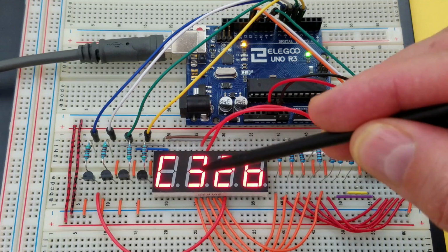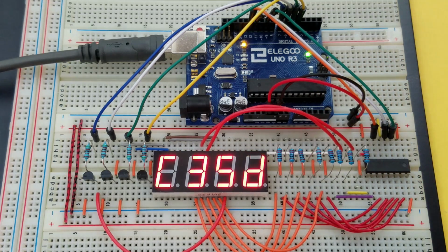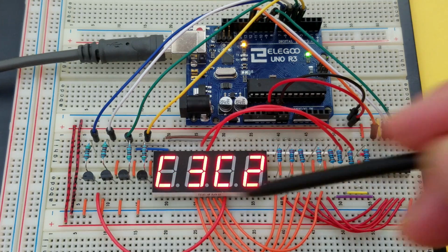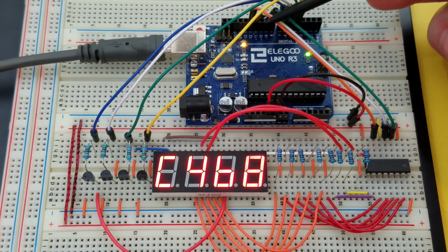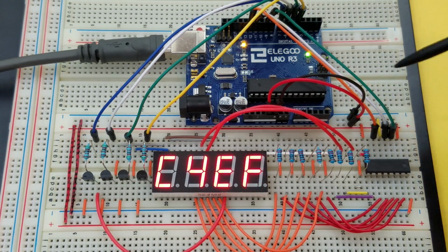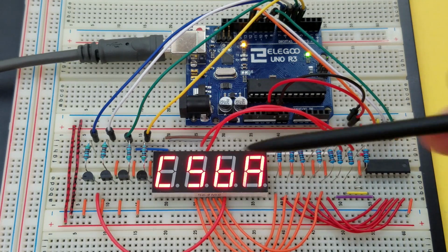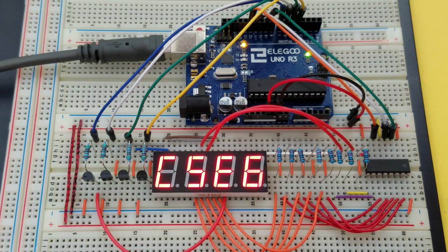Here's a hexadecimal counter. It's now counting up from 000 to FFF. The C is the raw data value that I sent to display. And the brightness, I believe, is at around 90. Is it right? I forget what I set that to. You can see I kept the pin modes or pins the same for the data, latch, and clock like I had in my previous sketches or lessons, but the shift register had to be scooted over to make room for all the additional components.